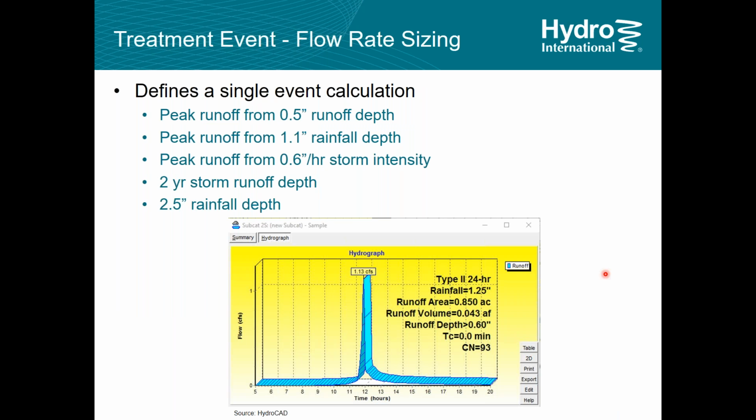So most stormwater manuals these days, we find, are starting to include manufactured systems. As they do revisions, they recognize that manufactured systems are part of the solution, part of the toolkit, and that a sizing method is often appropriate. Traditional manual writing usually works on a water quality volume, and these things are not volume based, they're flow through systems, so you have to convert that water quality volume somehow into an equivalent flow through rate.